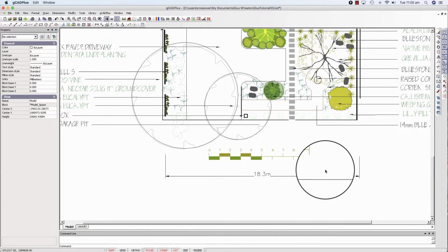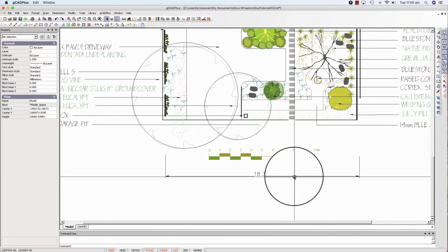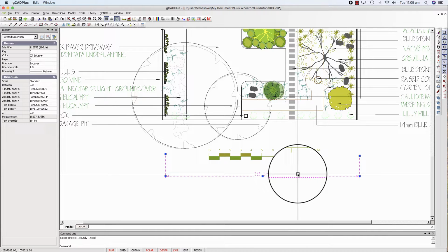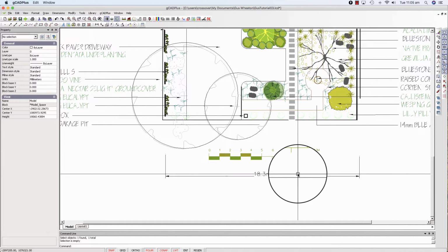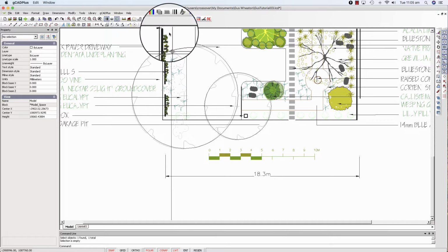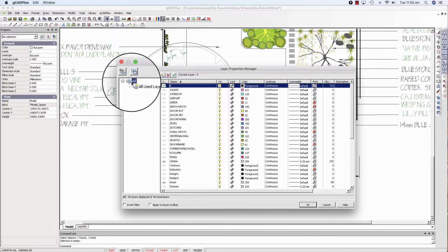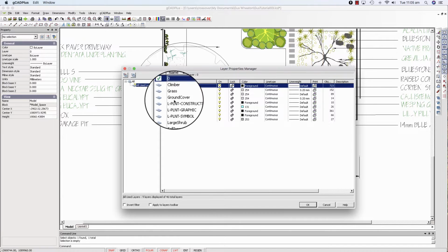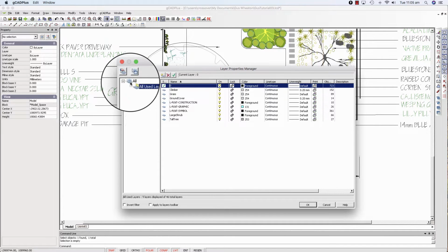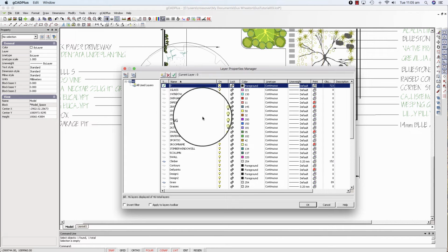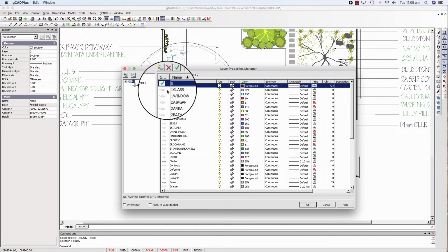Previously, when we've been working with this drawing, we played around and enhanced the dimension style, and we suggested that it's a good idea to put dimensions on their own layer. So to do that, I moved to the layer stack, and because the switch all was on, we were able to see a whole pile of layers with nothing on them, and we wanted to remove those. Mostly you would work with just all used layers.